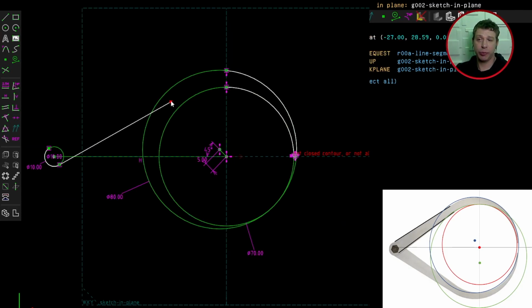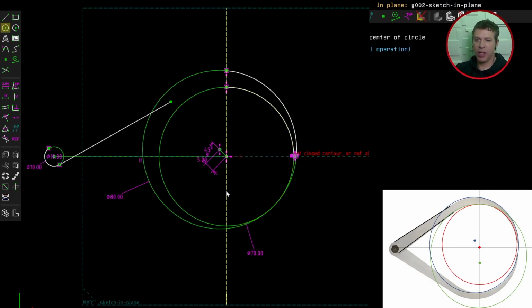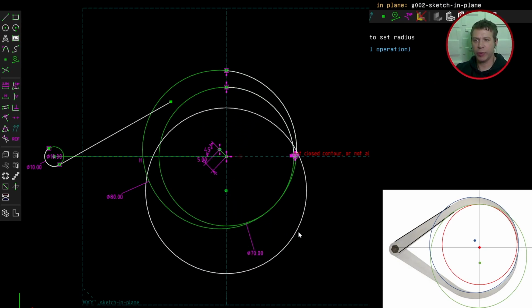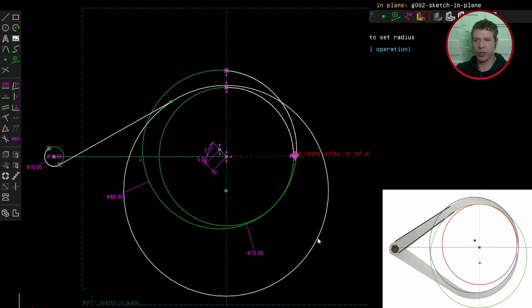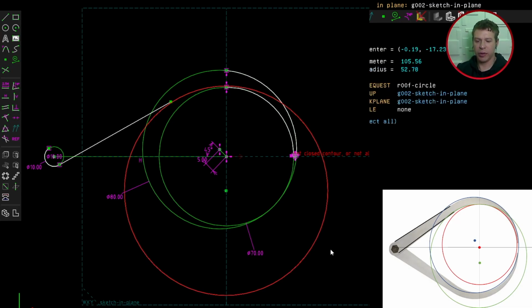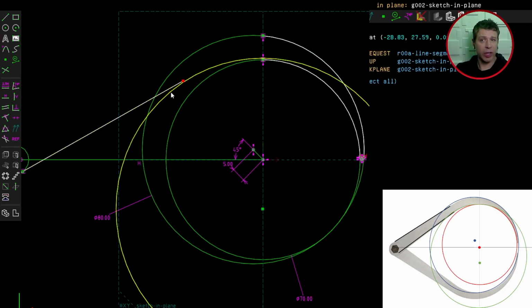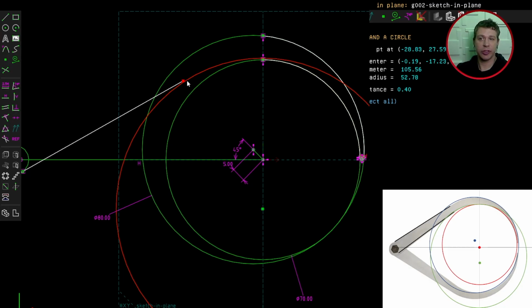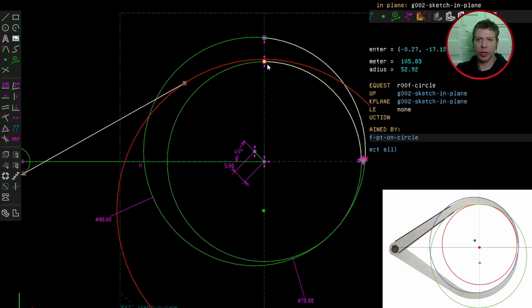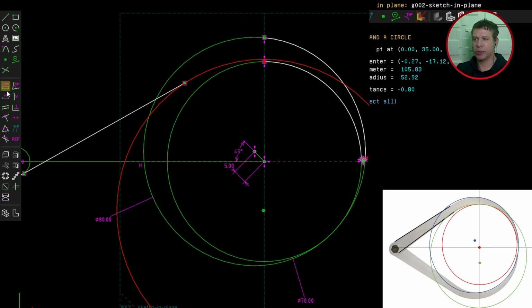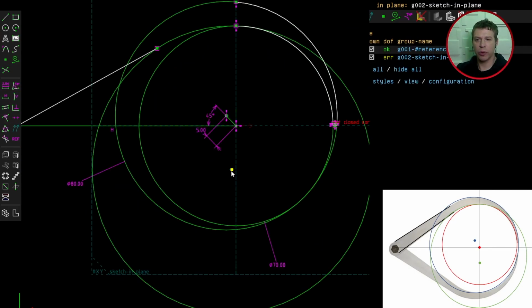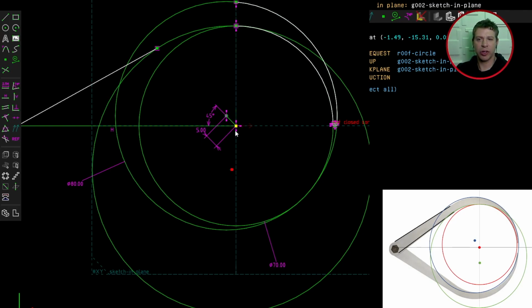Now we need another arc to bridge between these two points. In the plan, I had a circle that was down here somewhere, and if I draw the circle like this, you can begin to see that this may be correct. So I'll click on that circle, click G. I'll make the end of this line to be overlaid with this guide circle now by selecting the circle and the point and clicking constrain point on curve. And also I want this curve to be overlaid with this point. So select them both and click here again. So I'll constrain the center of the circle and the origin to be vertically aligned with each other.